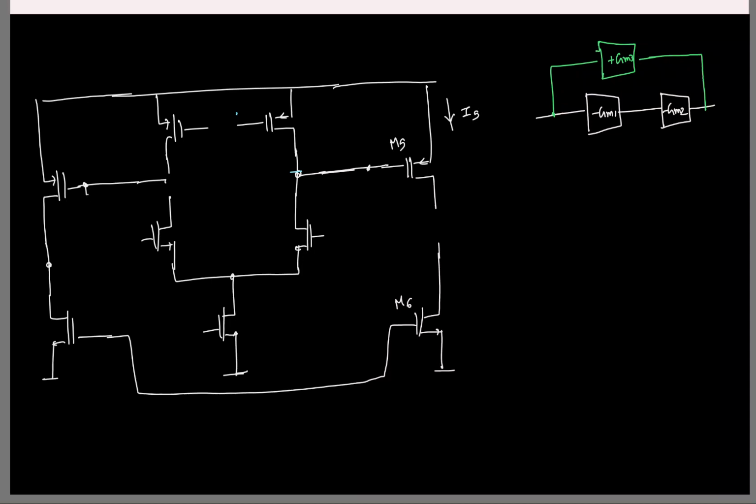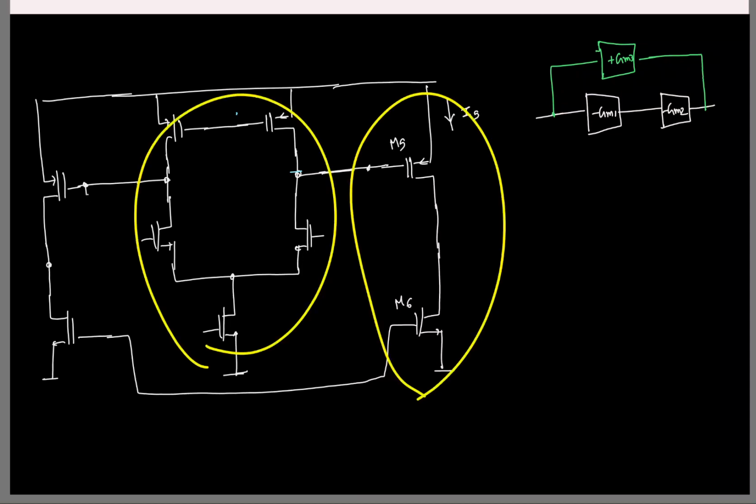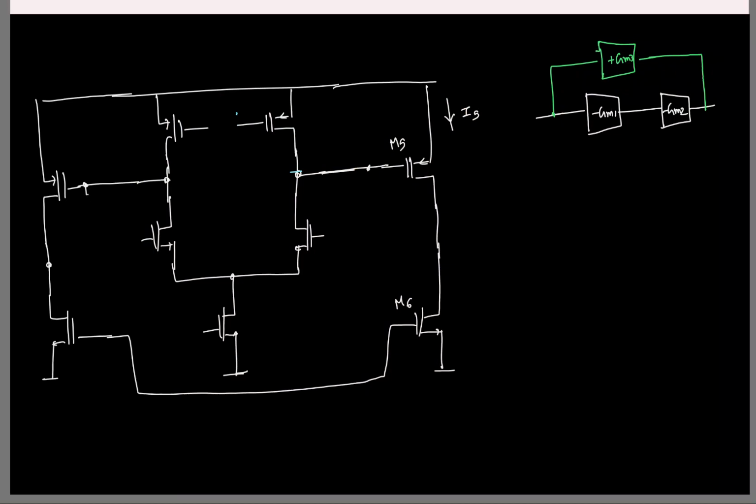So how can I add this third GM3 here? I have GM1, this is GM1, this is GM2. Now to compensate, I need to have the third GM3 connected from the input to the output. Can you suggest what I can do? What is the simplest GM you know? Not implementation of a GM. What is the simplest implementation you know?